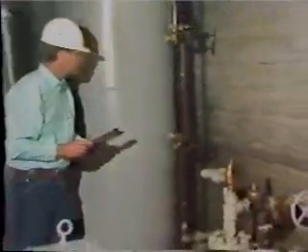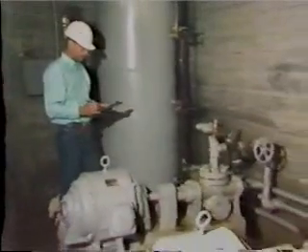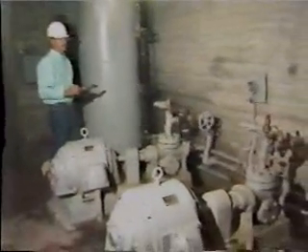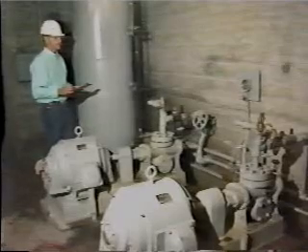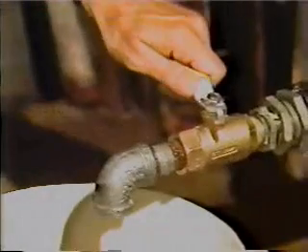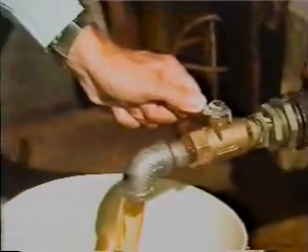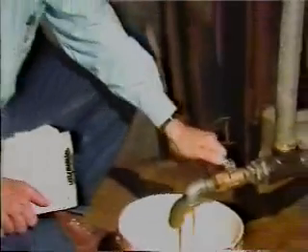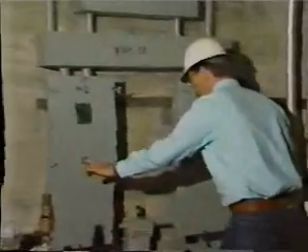As with a radial gate, when inspecting a slide gate, visually examine the operator, in this case, a hydraulic one. Hydraulic operators are usually in protected areas, so surface damage from vandalism is not generally a problem. First, look for condensation in the oil sump. Drain out the water and note the amount. Be sure to check the electrical controls for incorrect labeling, worn wire insulation, dirt, and broken, loose, or missing parts.